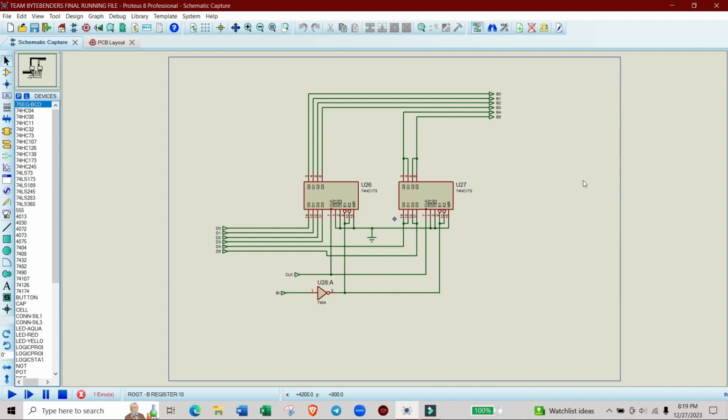and then execute the out instruction, which would write the value to the memory address specified by the MAR. To output a value to the display, the CPU would load the value into the B register and then execute the out instruction, which would output the value to the display. So this is how a B register works with accumulator.